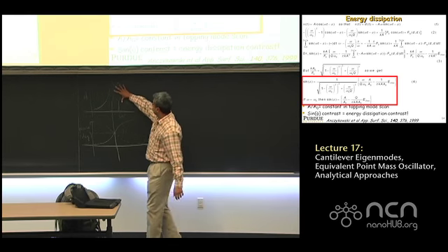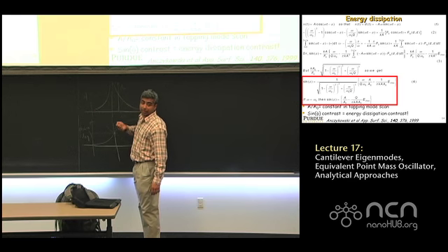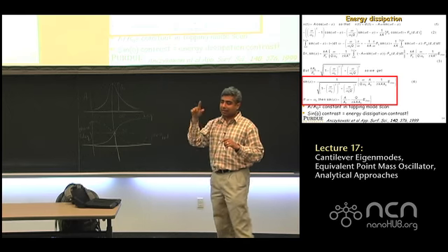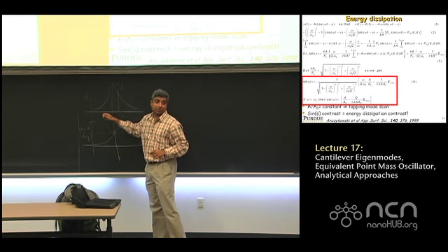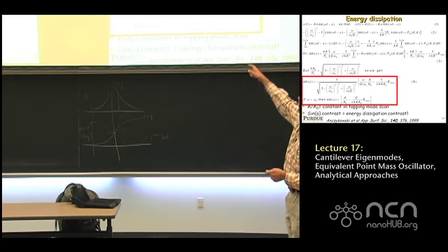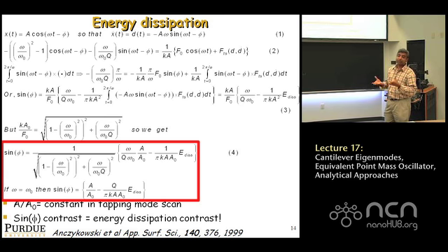So if you know this amplitude A0, then we know what force you're applying, because we have done the transfer function before. Remember, if you look at the magnetically excited transfer function, it relates the amplitude you get to the driving force. You can invert that and get the driving force F0 in terms of the drive frequency and so on, as shown. So k A0 or F0 comes from that analysis that we did without tip-sample interaction forces. So if you know the oscillation amplitude A0 when there are no interaction forces, you can back out the drive force F0.